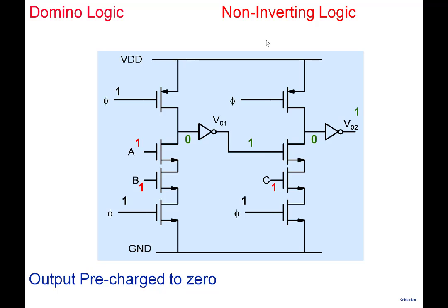At various points when you're building logic circuits, you need inversion. And this doesn't provide inversion. It only provides non-inverted outputs here. A plus B or A dot B and all that. So that's the problem. So somewhere, what you'll have to do is use some other logic family, a regular CMOS. And by the way, note that we have used a regular CMOS inverter here anyway. It's not a pure dynamic logic. So it's a new logic, but a CMOS inverter has been used. And similarly, wherever you require a logic inversion, you'll use a regular CMOS inverter to invert it.